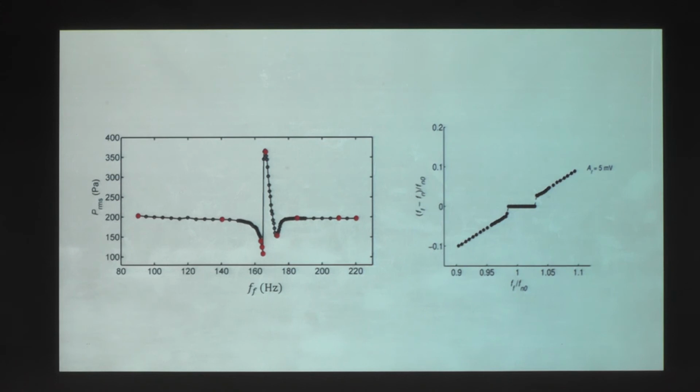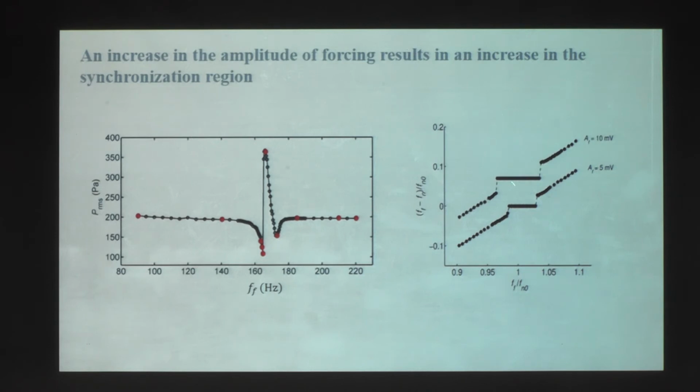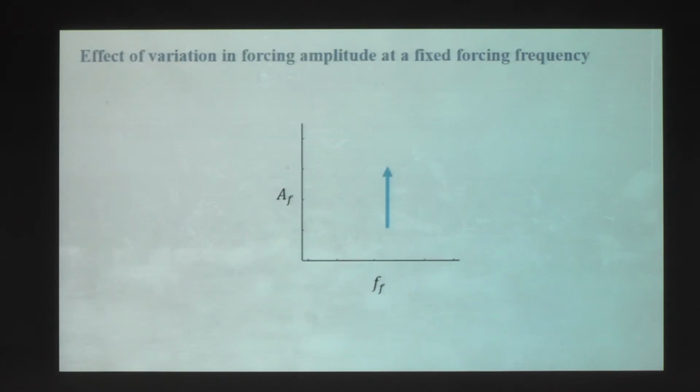So this is for one forcing amplitude. If we increase that amplitude, basically this forcing regime is increasing. That is quite expected, because we are going to have a V type of synchronization regime. So from this plot we can slightly conclude, though we have to refine this conclusion, that if we force the system close to the synchronization boundary, there is a possibility of mitigation of thermoacoustic instability.